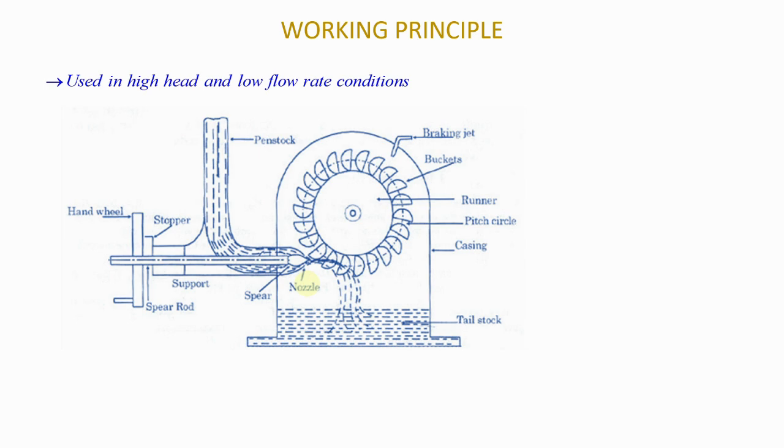And so you can see that the jet of water from the nozzle is from left to right. Okay, so this water is ejected from left to right. And then when it goes that way, it comes and makes an impact with the buckets. And because the impact is from left to right, this causes the buckets and the wheel to rotate in the anti-clockwise direction.